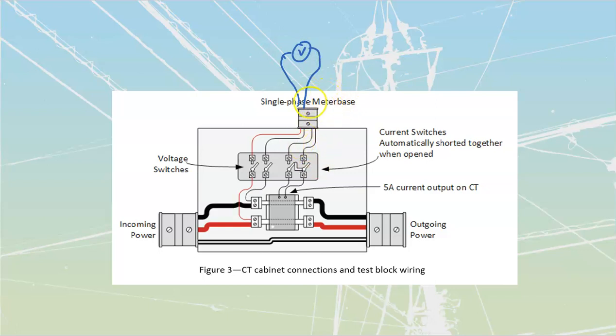The other two lines over here are going to be fed into the amperage section, and then the meter is going to multiply volts times amps together and display that as watts. They also have the ability to measure in-phase versus quadrature types of currents. They can tell when we have a lagging power factor and how large that magnitude is, and anything like that as well.